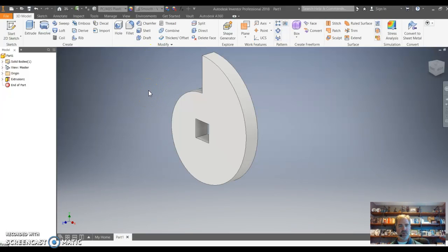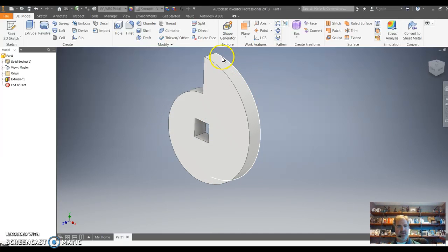All right. And the other thing needed for the assignment is you do have to create some work planes. So I'll go ahead and demonstrate that while we're looking at this. And you want a work plane, and hopefully you use the origin because that makes it a lot simpler to place a work plane, because I want a work plane that's going vertically, one that's going horizontally through it, and I may also want one that's kind of slicing it in half.